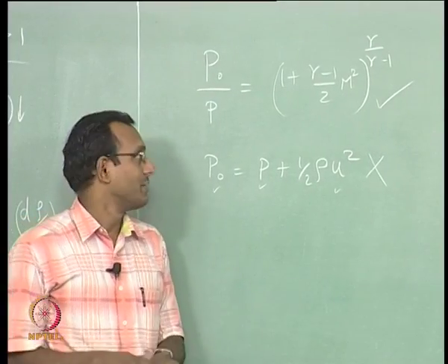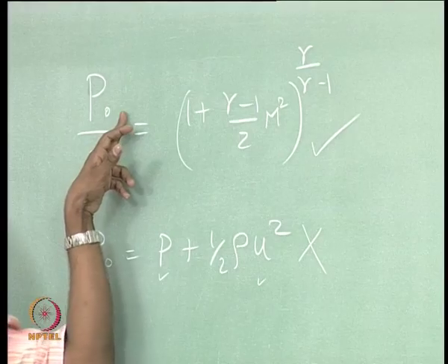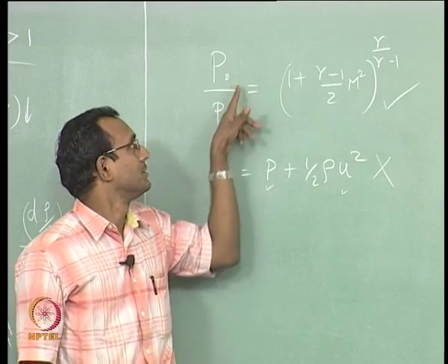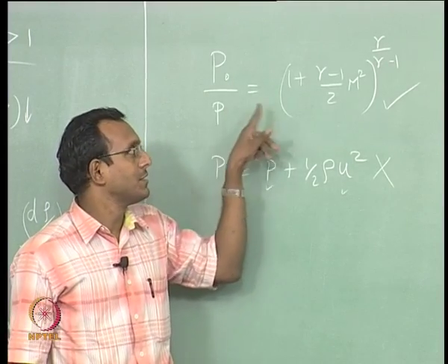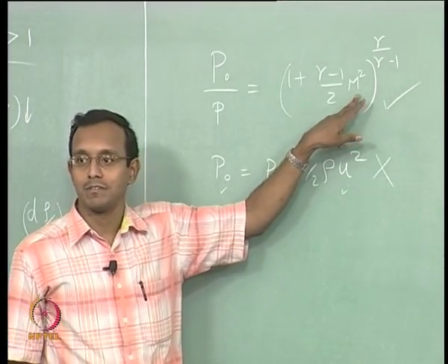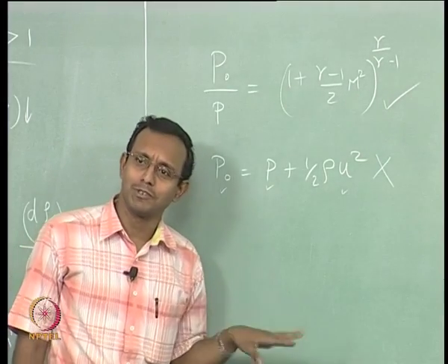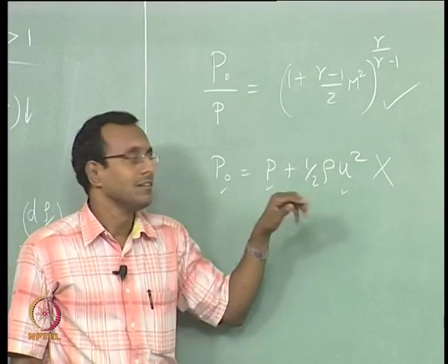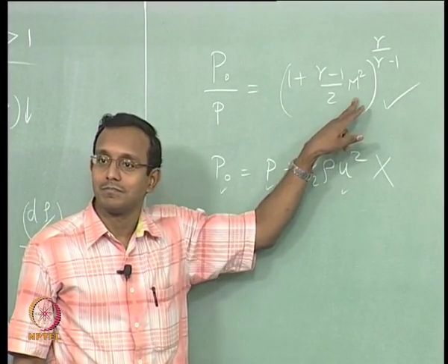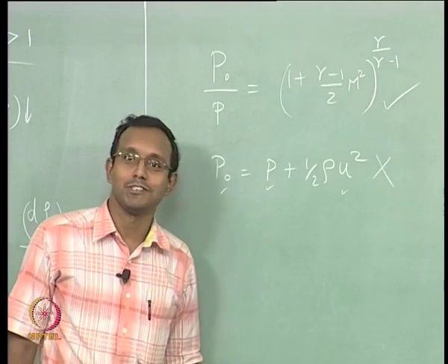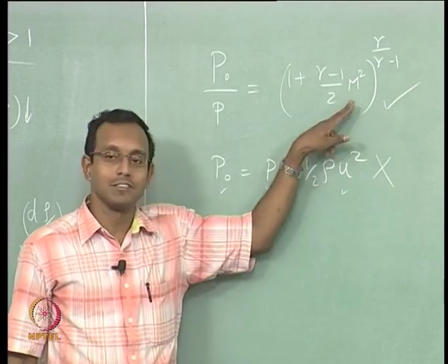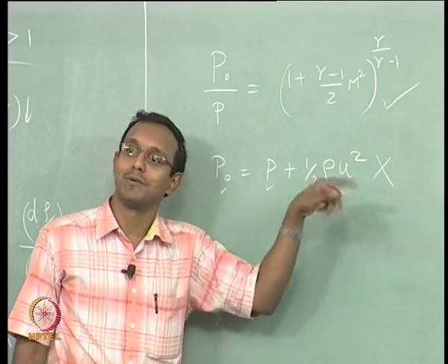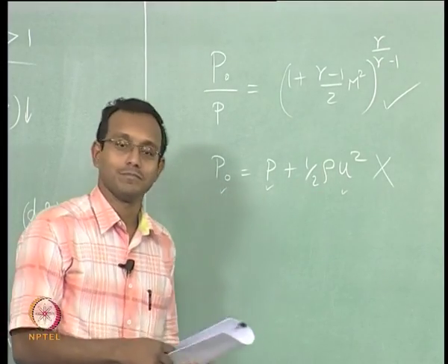Okay. So, if you are given a static pressure and a stagnation pressure, I have already defined these two variables, right? Yeah, I think so. So, if I am given these two variables, I am going to find Mach number from there. Even if it is very low subsonic, this formula works correctly. Okay. We can do that even if that is the case. Even if the Mach number is 0.0001, it will still work. It so happens that this also works if it is Mach number 0.0001, that is all.